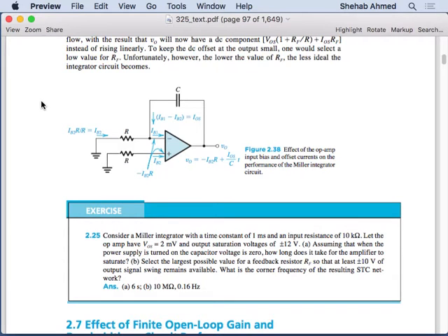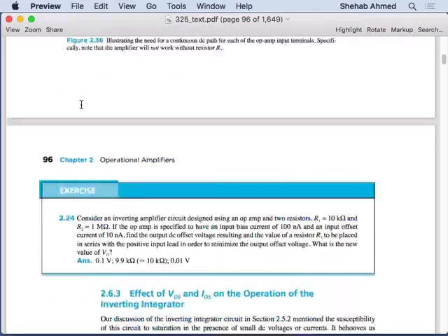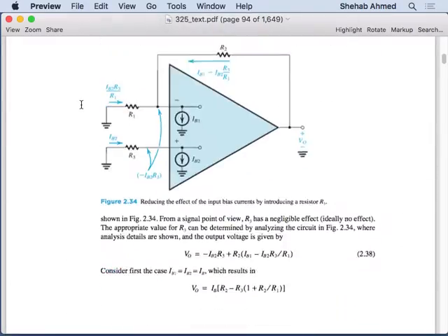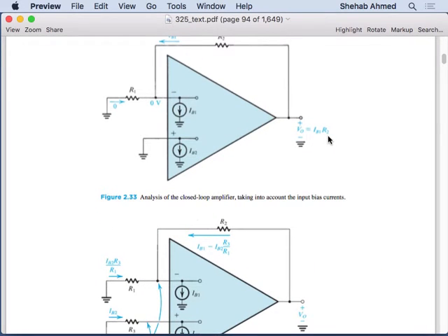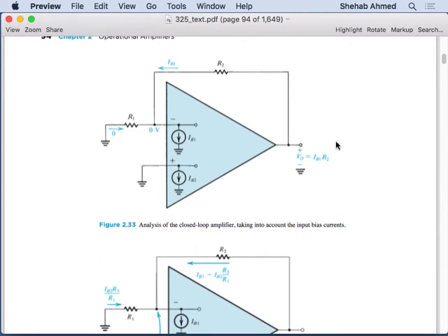Same thing with the bias current. With the bias current, we initially were passing the full bias current through the op-amp. So we were passing the full bias current multiplied by even the gain through the op-amp, which was a problem for two reasons. We were passing through the bias current as well as having a constraint on R2 that is contradictory, right? The constraint on R2 was to try to make R2 small so that the bias current doesn't pass through with the gain. At the same time, R2 small is conflicting with us trying to create a larger gain for the amplifier. So we said, okay, this doesn't work.